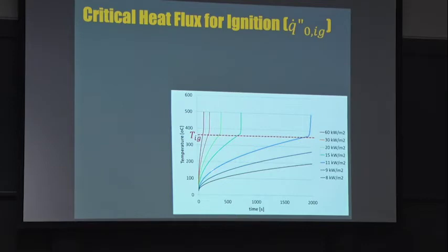You're going to get the critical condition when you reach thermal equilibrium at the ignition temperature. And you're going to get the cases where you will exceed the ignition temperature if you could, if it didn't ignite, because you have more heat than the one that you're losing to the ambient. Okay? So this point where ignition happens, this is the ignition delay time.